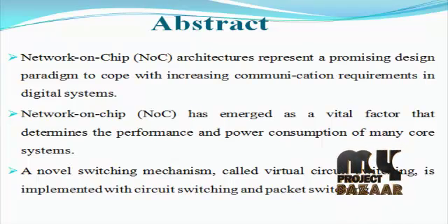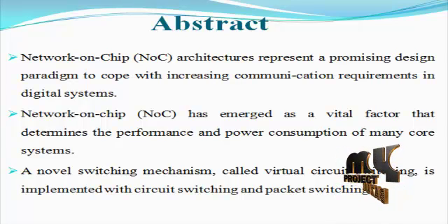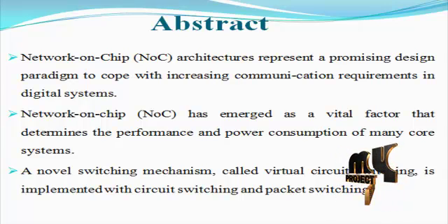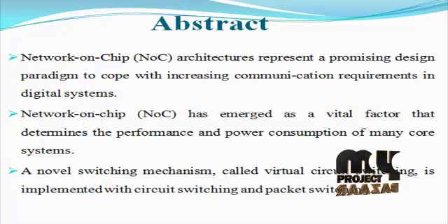Now we discuss the abstract for the project. A 2D mesh on-chip topology is characterized by a relatively large average distance between nodes. When the network size increases, long distance traffic suffers from high transmission latency. Moreover, the blocking probability in wormhole routed networks increases.